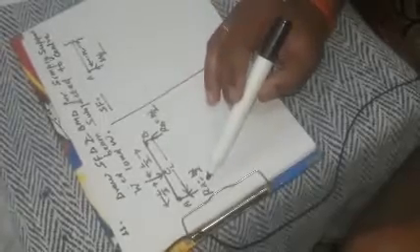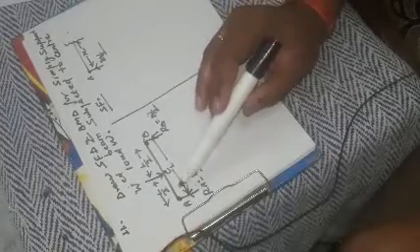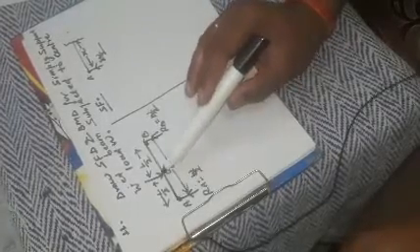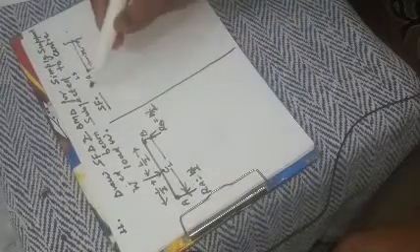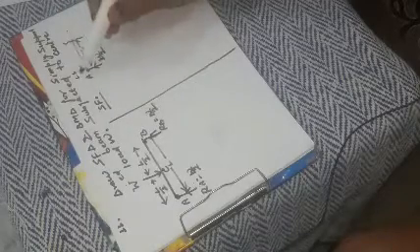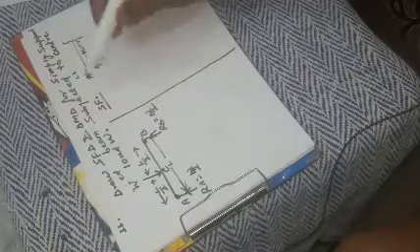But the effect of load RA, W by 2, is starting from A to left of C, right? So we are considering first segment just left of C. So this is our left segment, because we are moving from left to right. So sign convention of left segment will be applied for shear force and bending moment. Clear?